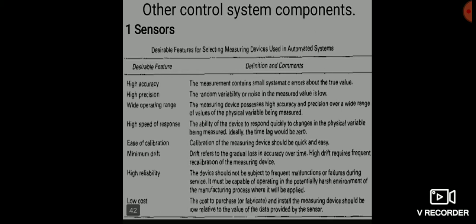Discrete sensor devices are often divided into two categories, binary and digital. A binary measuring device produces on and off signals. The most common device operates by closing an electrical contact from a normally open position. Limit switches operate in this manner.